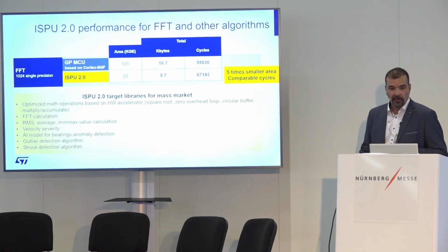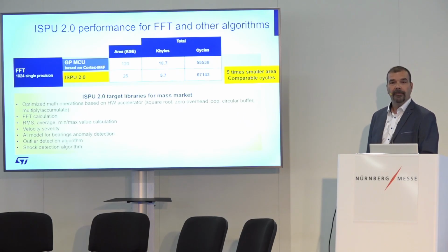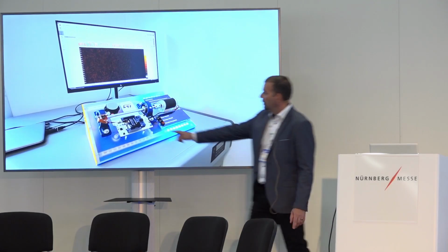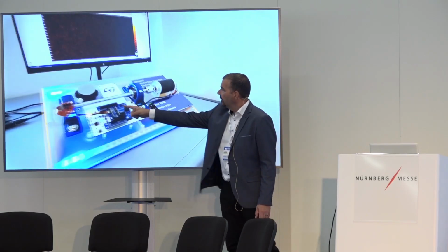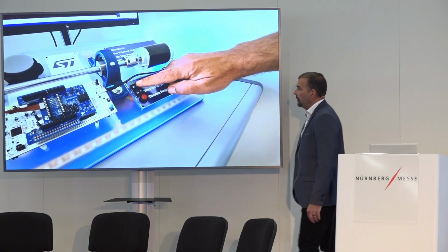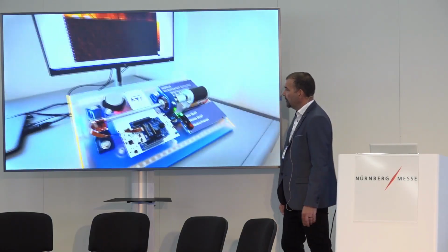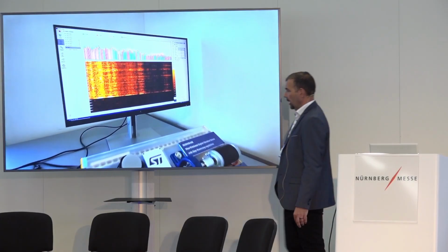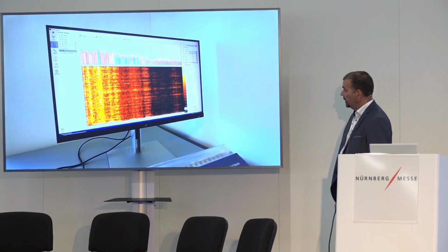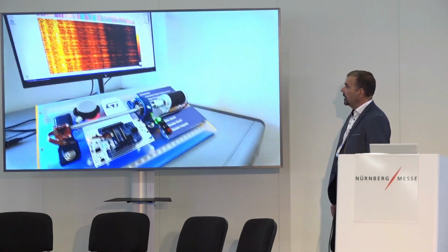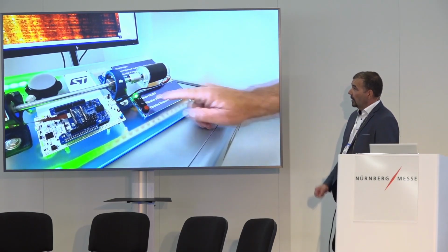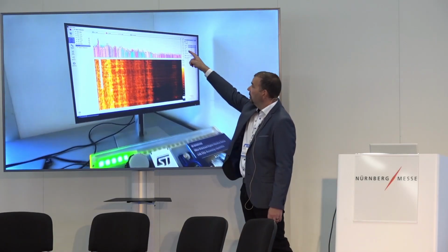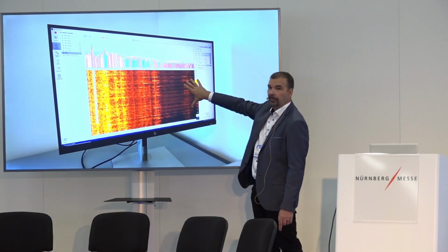Okay, now I suggest to have a small look at our demo, which we have on our booth. It is a demo which is showing our sensor in action. So this is the sensor. We have a bearing set up on the motor. And we are, of course, spinning the motor. And we are simulating the failure of the bearing by a piezo actuator. You will see later on that we are intentionally generating some frequencies. What you can see in the GUI is the FFT, so the frequency spectrum calculation, and the time spectrogram.